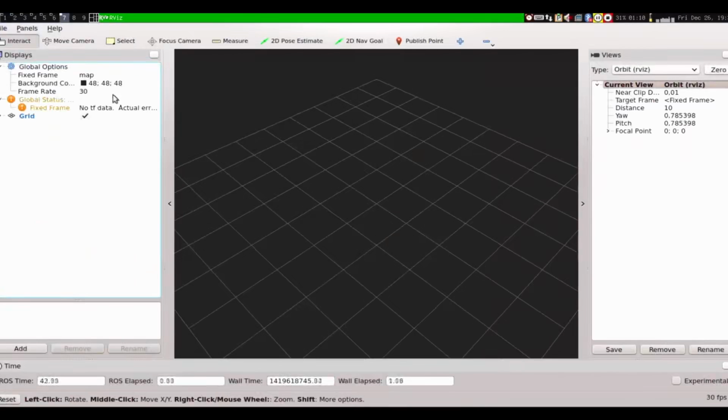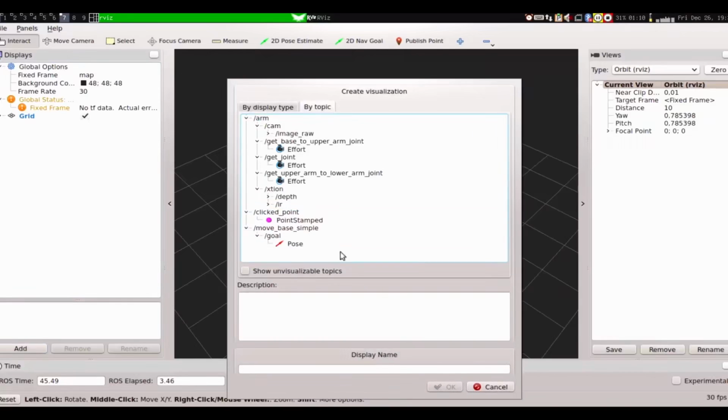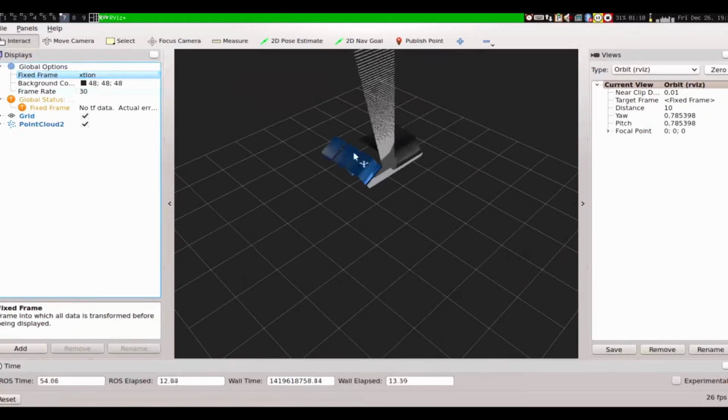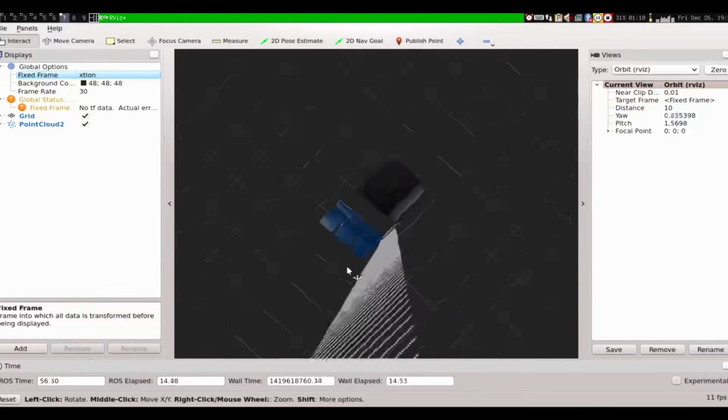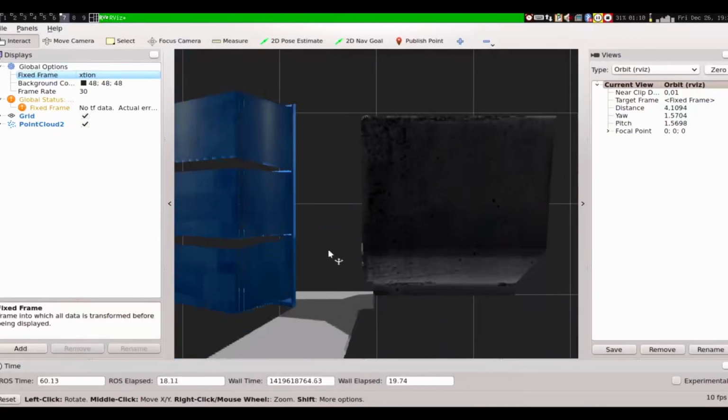So you can use your software one-to-one as you use it in your real robot, run it against a simulated robot within a simulated environment, and thereby ensure that if you change the code, nothing breaks, not only on the level of it still compiles, but on the level of the robot still does the correct thing.